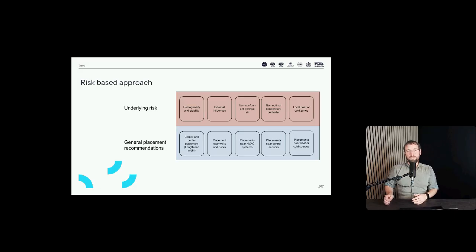So to take an example, we would often during a study find out that there's a corner where it's normally the hottest and one where it's normally the coldest. So if we place two sensors at those positions, we should, with a reasonable degree of certainty, be assured that all other temperatures are within those two points. So if something happens and everything gets hotter at the same time, the hottest spot we found during the mapping should be the first place where we would be able to measure a higher temperature.